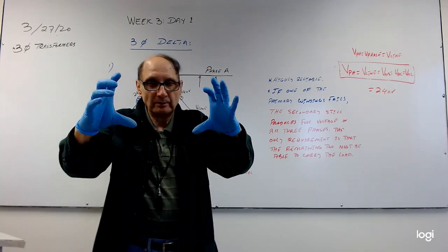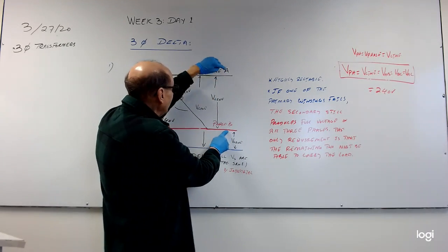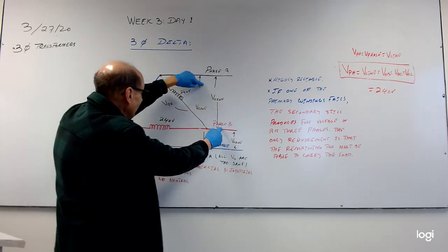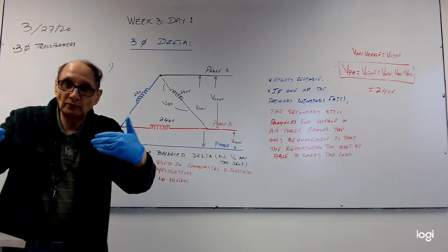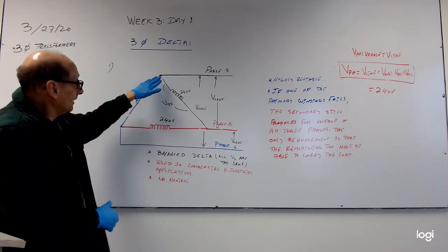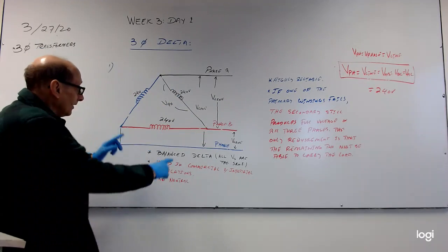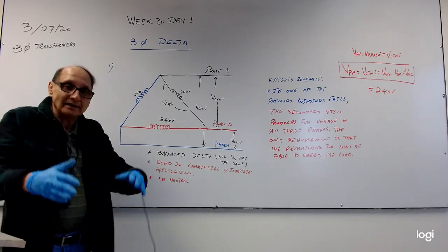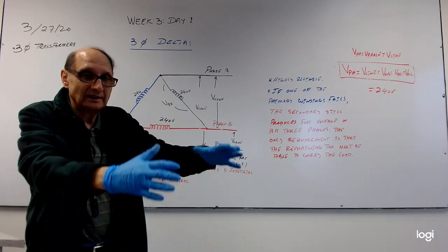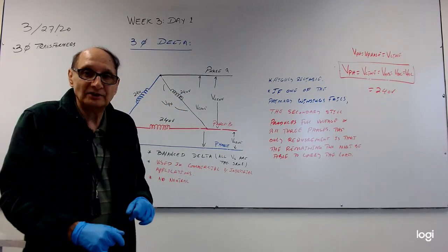Again, some people call it line to line voltage, between this line and that line, which is the same as across this terminal. So if I give you a voltage across any of these 2 points, the same voltage is going to appear across all of them in a balanced system.